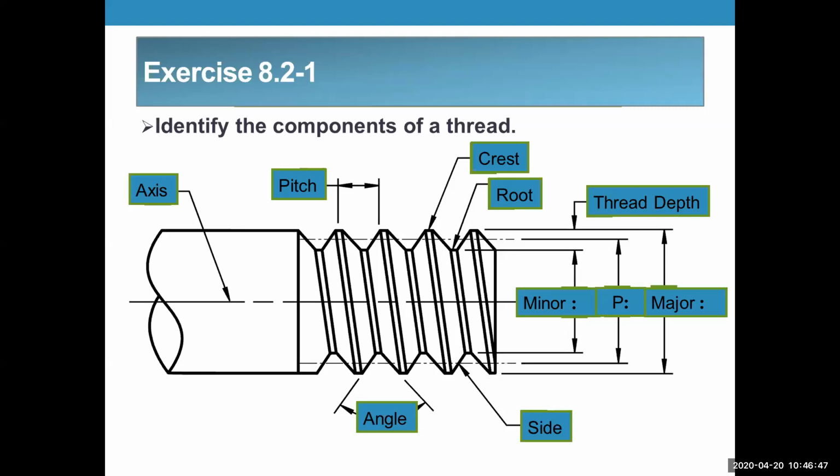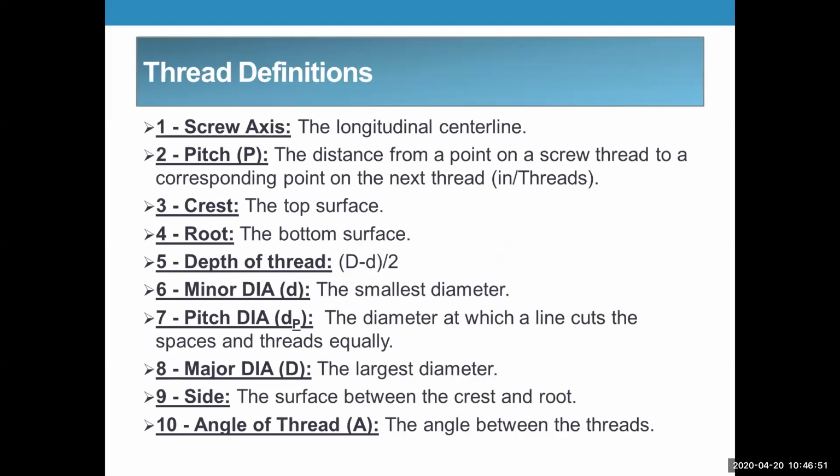It's a really strong thread, though. If you look at a lathe, and you look at the shaft that has the half nut on it that you use to cut threads on the piece that's chucked up, the threads on that shaft are square threads, because they are strong, and they can be very accurate.